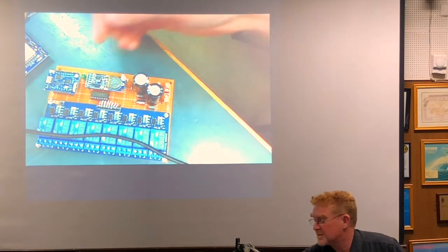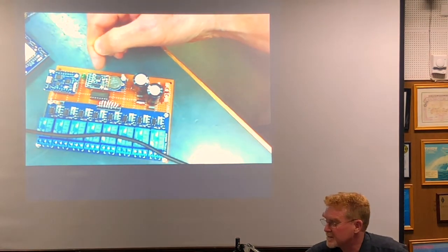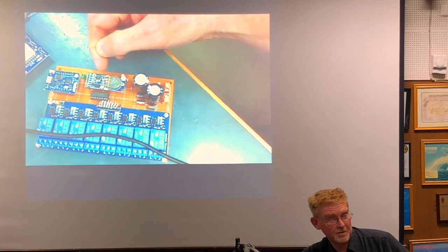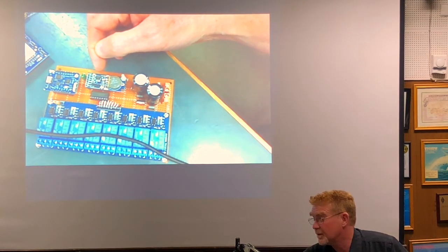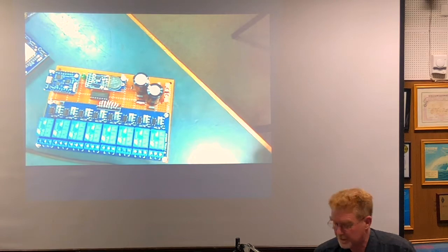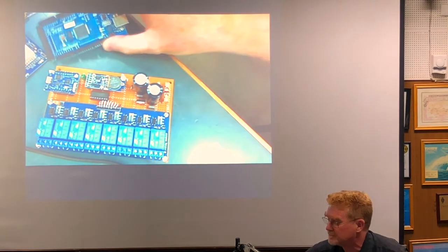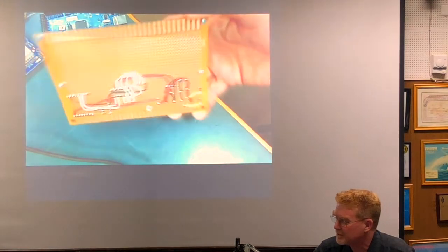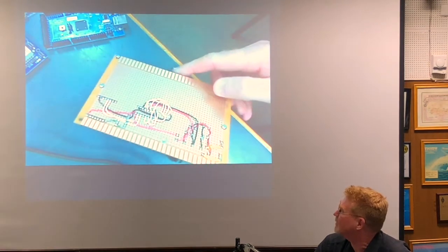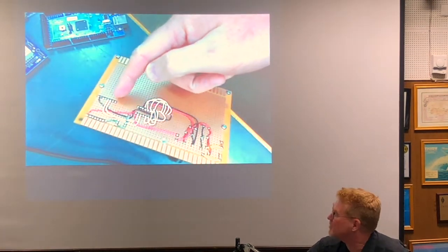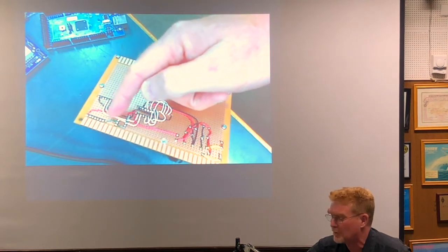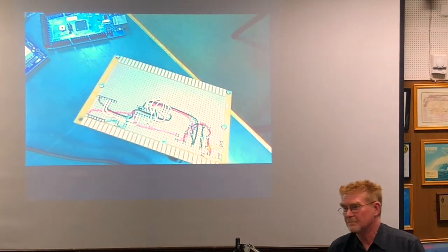So that's a $6, $7 Chinese module. That's an I2C connected real-time clock. I2C is really, really good because unlike things like the Mega I showed, with all those nice I/O connectors, this guy underneath, look, that's that module I mentioned. Those two wires coming off, the white ones, that's all the I/O I'm using.